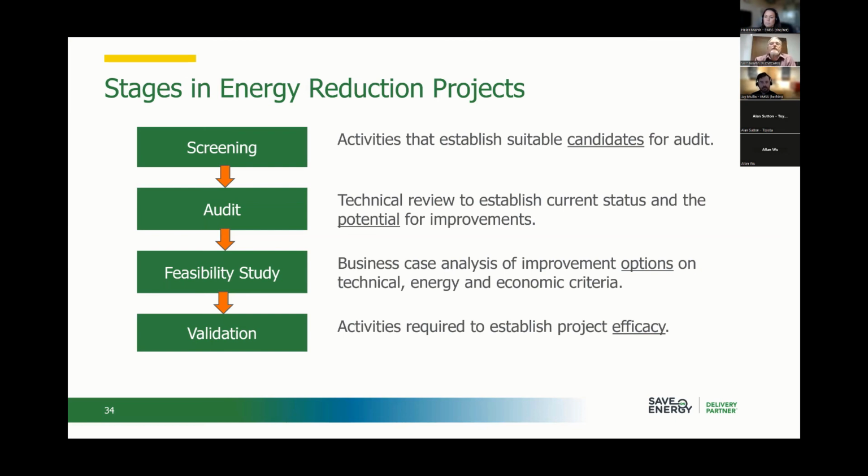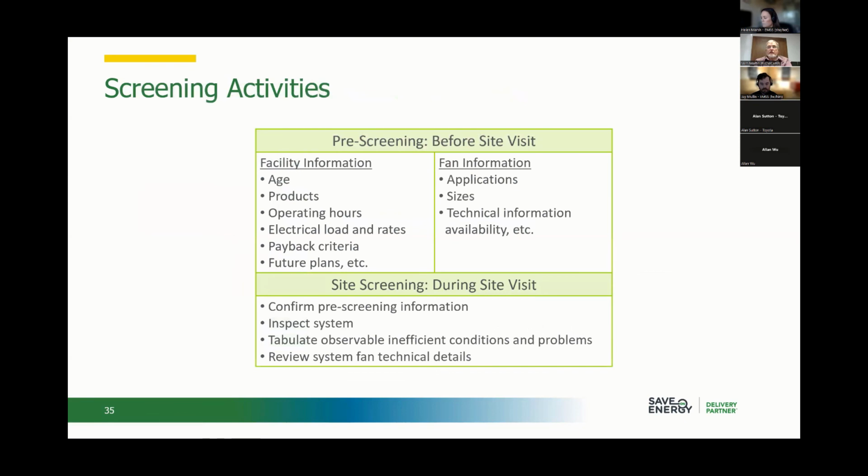If you go to the next one there, I talk a little bit about screening and what's involved with this. So we're consultants here, so we look at stuff through that lens of being consultants. Before I go on a job site, quite often we're getting the phone calls going and the emails going: okay, how old is this facility? What do you make? How many fans have you got? What are the products? What are the operating points for these fans? Do you have fan curves? Do you have fan drawings and so on? That's all stuff that we want to see laid out before we get onto the job site.